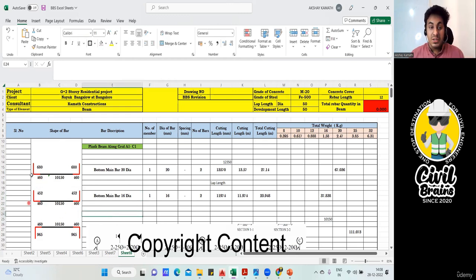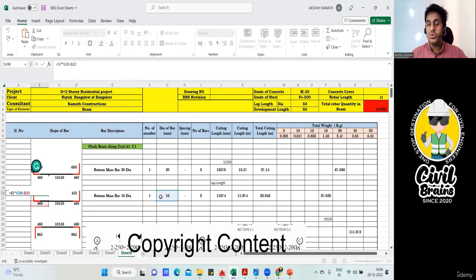Where will the changes come? The changes will come in this L shape, because this L shape is completely 57 times the diameter of the bar. So here, 57 into 16 it will take. You do it manually. If you're not able to, I'll do 57 into 16. It is 912. So 912 minus 460, I should get 452. Practically, I got on the Excel sheet 452 and 452.